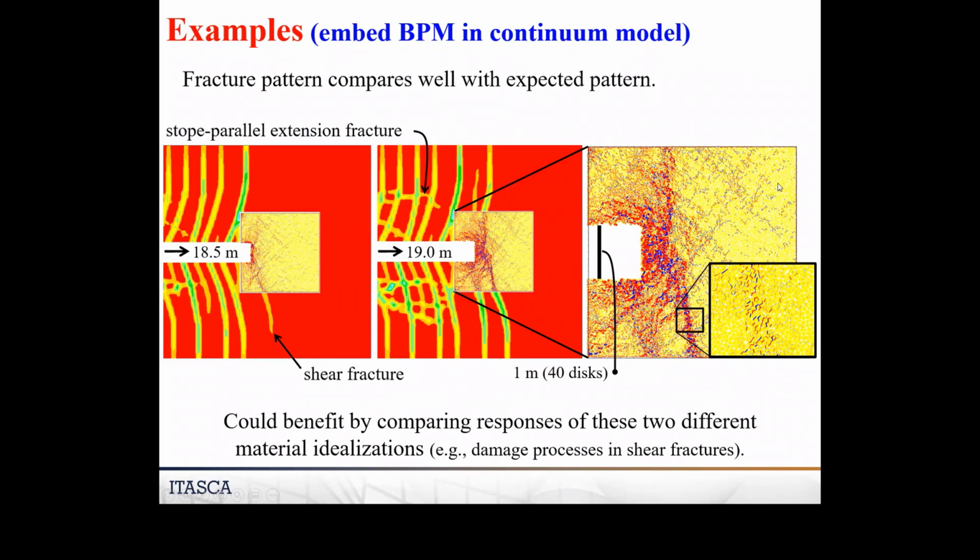This is the type of thing that we see when we do these models. Here's the model, and we advance the stope, here's the model, okay? And so what we're seeing here is these shear fractures that form. Basically, the stresses are so high that when you move this forward, the material wants to push in, and so it pushes in and forms these shear fractures. They're spaced at about the same distance as the advancement rate of the stope. They really see these underground.